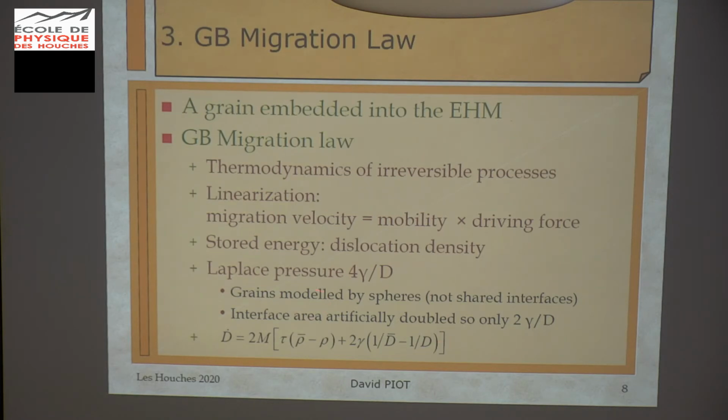So the interface area is artificially doubled in this kind of model. So in fact, one has to divide the Laplace pressure by 2 in order to evaluate things correctly.